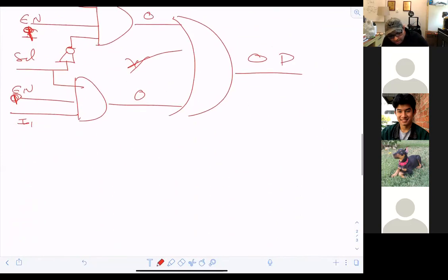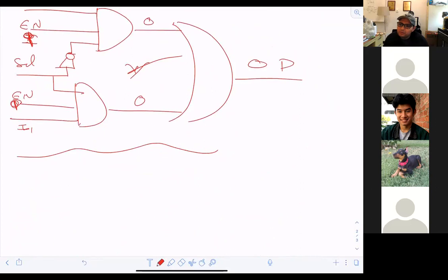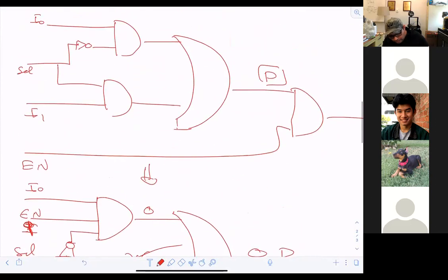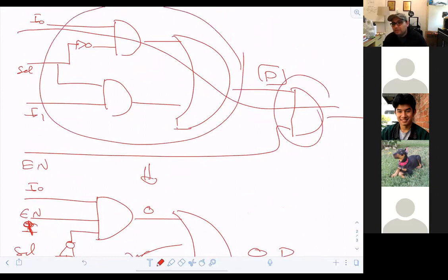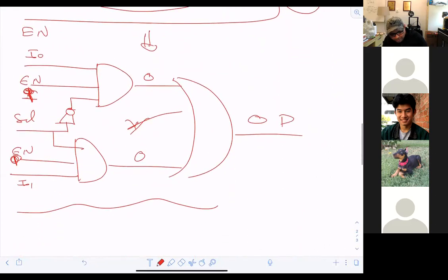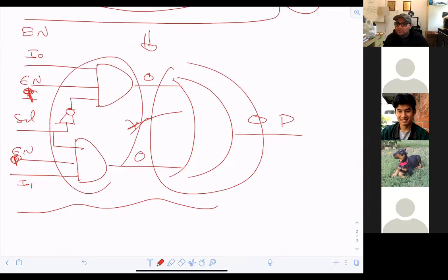But this circuit is kind of stable, because most of the paths almost look like each other, while this one has a very long path, which is this one, to be a critical path. And frankly speaking, this is actually a working circuit, and then you are disabling it, while from here, I disable the OR gate, and those ANDs will be doing the job. Do you guys agree?